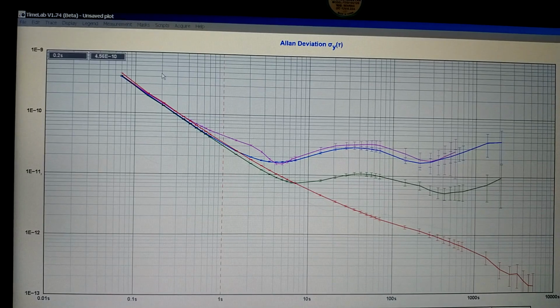In a previous video, Nerds 96, I tried to use the 5370A from Hewlett-Packard to measure Allan deviation. And the results were a little bit questionable because I was using the wrong drive routine and could measure only very precise oscillators that were on the same frequency, because there was occasional loss of data, so the phase had to be constant over the entire measurement to make a lost data point disappear in the noise.